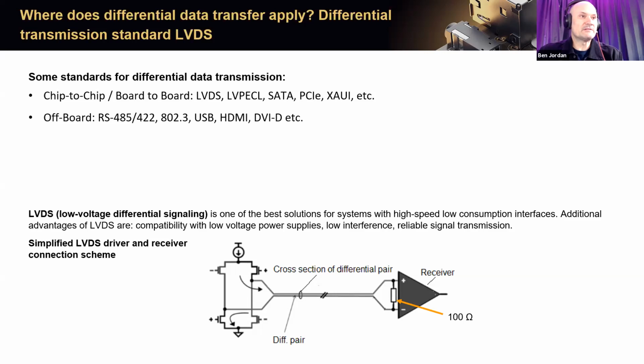Also, the transmitter looks like an H-bridge, where we can send and receive current in the loop, but it's all coming from VCC and sinking to ground. So whether you like it or not, a differential signal on a PCB is not just two signals. It's not a true and a complement. It's three: true, complement, and their reference ground on a PCB.